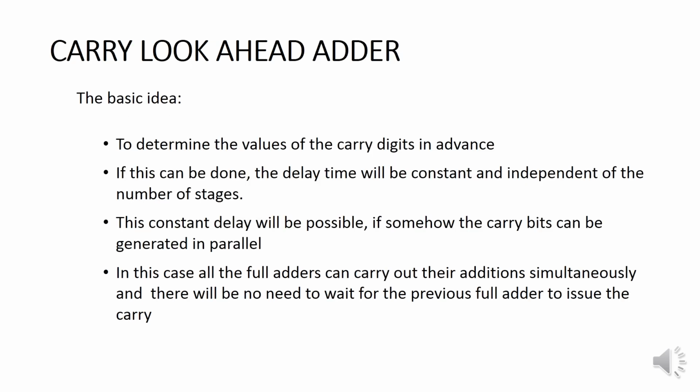In an effort to reduce the delay and speed up the process, engineers and designers came up with a new approach called carry look-ahead adder. As the name implies, the aim is doing some kind of look-ahead to determine the values of the carry digits in advance. If this can be done, then the total time delay of the adder can be reduced from roughly proportional to the number of n stages to the order of 1, which means in this case the delay time will be constant and independent of the number of stages.